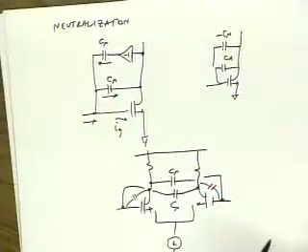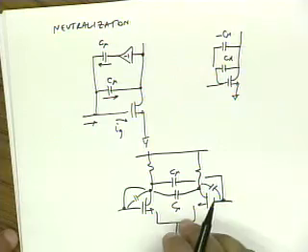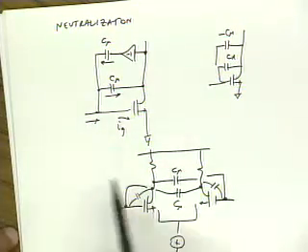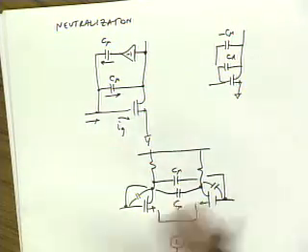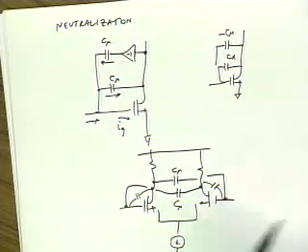All right, any questions? Does that make sense to everybody? And there's other ways to do it. We won't go into details. You can use transformers to provide phase inversion, for instance. You could use center-tapped inductors. So there's lots of tricks that you can play. Okay.